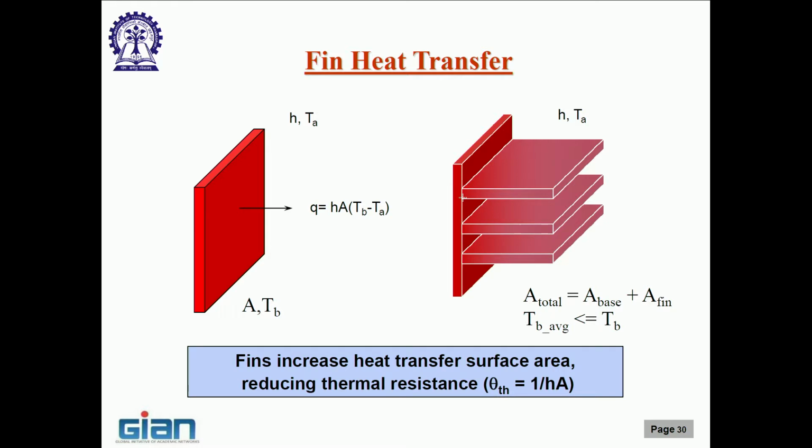Okay. There may be some contact resistance at these bases as well, because it is not always extruded from the same piece of material or machined out. Machined out is actually a very inefficient and expensive method, wasteful method I would say. But even if it is extruded, many times, especially the one that I have passed around, you cannot extrude those because these are extremely thin and tall fins. So, there are other ways by which this contact is not perfect. So, you need to add a contact resistance, and as a result the fin will be at a lower temperature compared to the base. But all this taken a little bit here and there, overall fins help in improving the heat transfer by making available extended surface area. Okay.